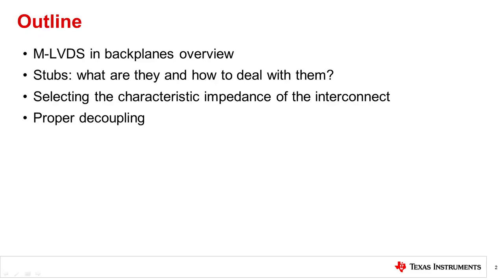I will start with a quick overview of MLVDS technology. Then I will talk about stubs, what they are and how to minimize their effect, as well as how to select the characteristic impedance of the backplane interconnect. And finally, I will talk about the use of proper decoupling to reduce power supply noise.